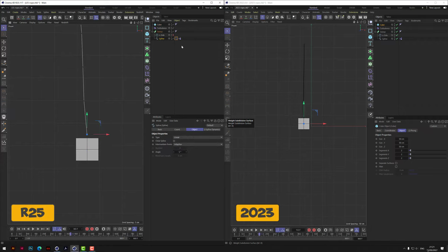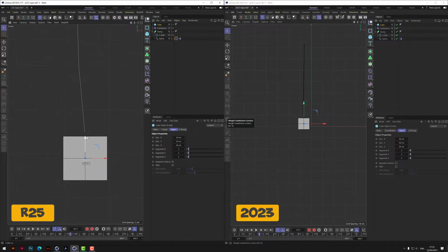Select the bottom one, and now click on the constraint, and then where it says object here, we need to drop in the object that we want it constrained to, which is the cube. So we drop the cube in there, and let's just move the cube up so it's like touching. So we go back here, cube, and now we say set.